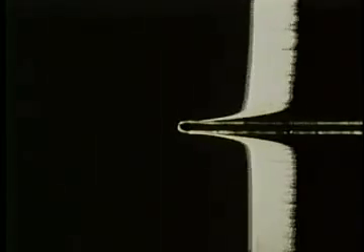The thickness of the boundary layer increases along the length of the plate. Fluid deceleration is transferred from one fluid layer to another by viscosity. Moving the camera with the free stream velocity will give a better view of the boundary layer growth. The velocity throughout the boundary layer is less than that in the free stream.